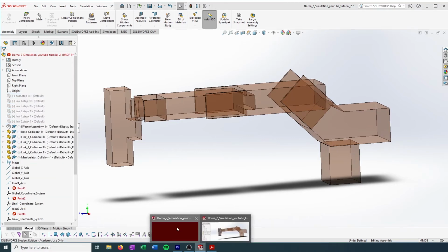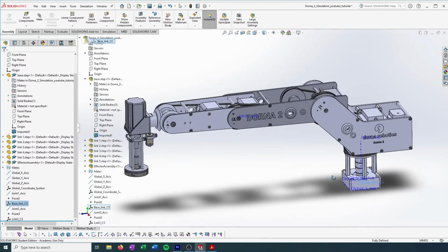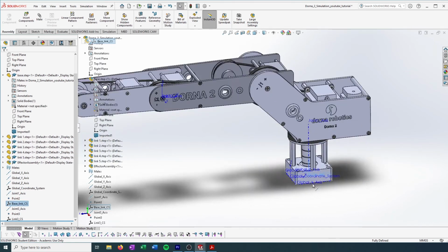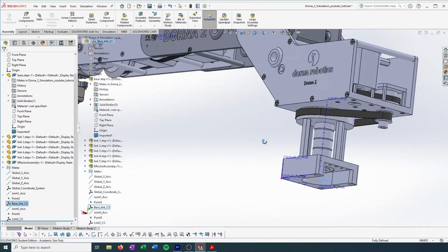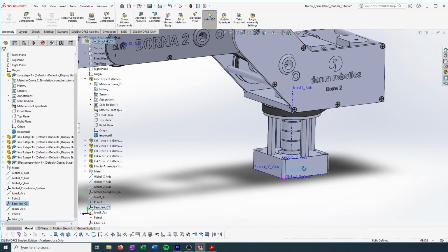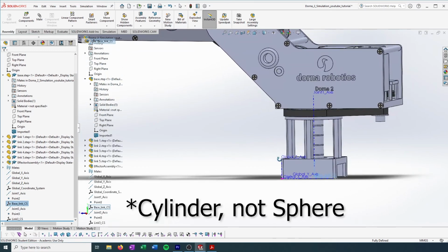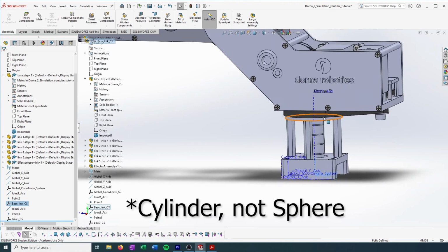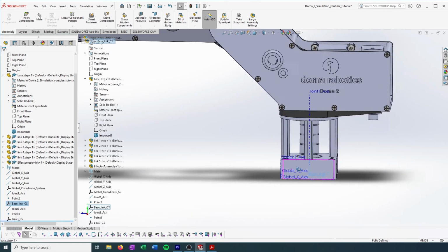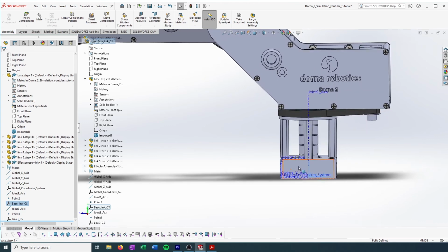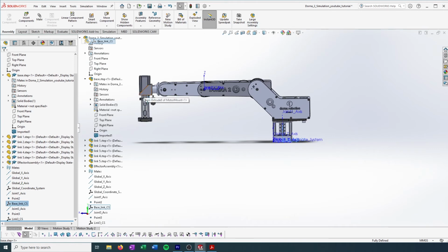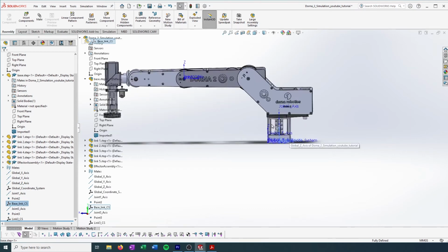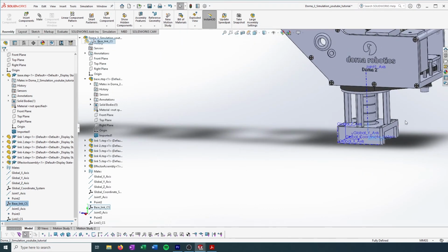So let me switch over to my tutorial robot. Okay, so this is what I had in my tutorial before. So we want to add a collision file for this base link right here. Your thought process is you want to create a box or a sphere, depending on the part, that will completely enclose that part using the least faces possible, but would still allow a fairly accurate collision. Obviously, I don't want this manipulator to get into a space where it can collide with this component, for example. So I want to just make a box just big enough to enclose this thing.